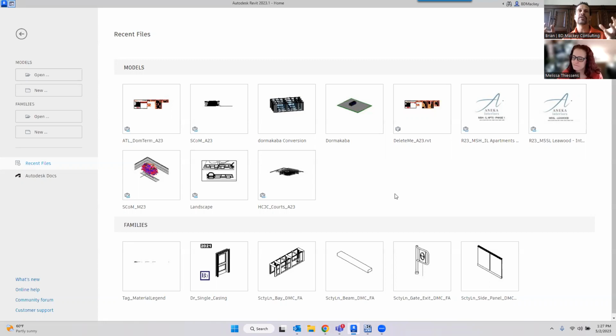It's a tiny building. But I then had finishes on the inside. So the inside wall finishes were all done with individual walls, so all my interior finish was different than my exterior. But I did do the core, the metal at the bottom, and whatever it was at the top, all as a stacked wall going around. Then everything inside was its own wall. So it was like 5 walls to do it. But yes.